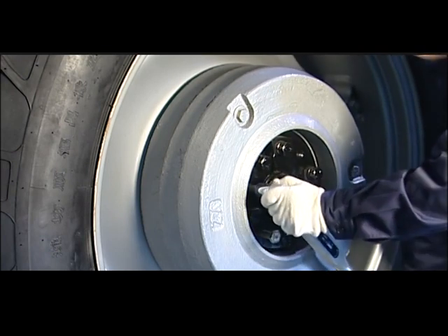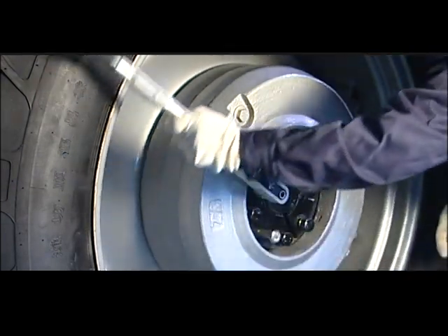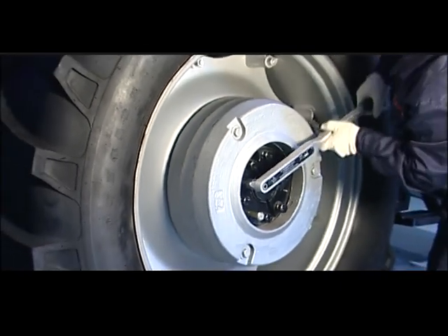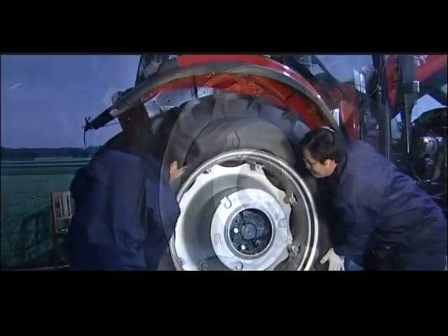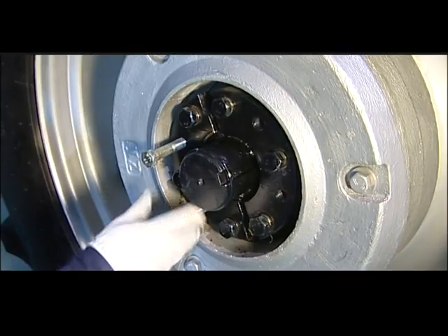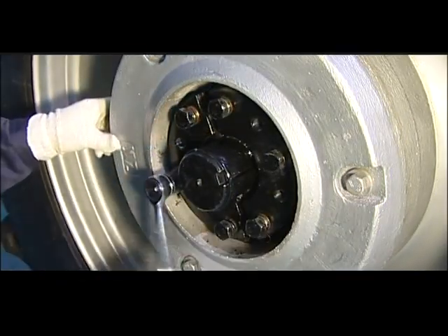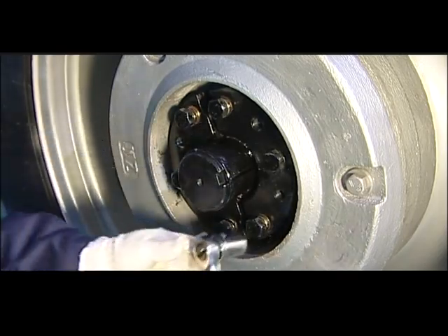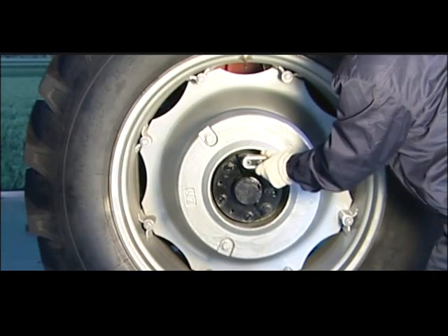If the lower bushing does not move, strike the head with a heavy hammer several times. Then loosen the bushing. Adjust to the desired tire distance. Screw off the M16 bolt. Screw down the fixed screws at the bushing, and tighten the screws with a spanner according to requirements. Attention!